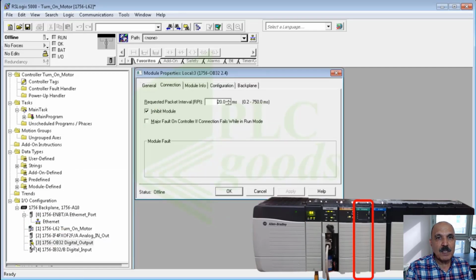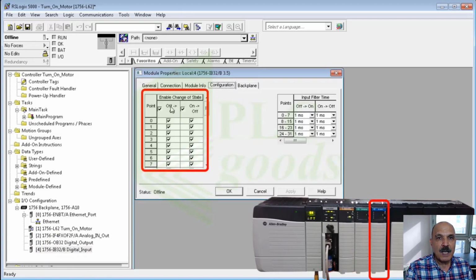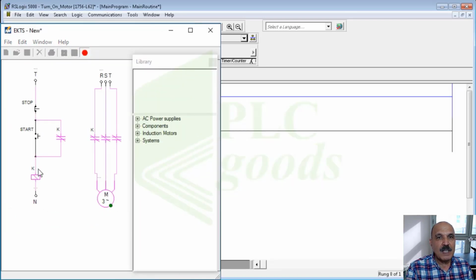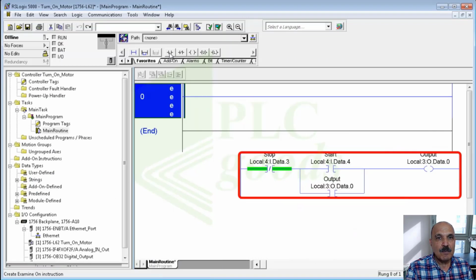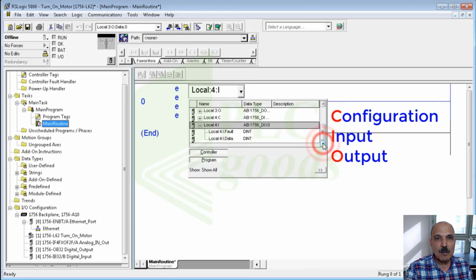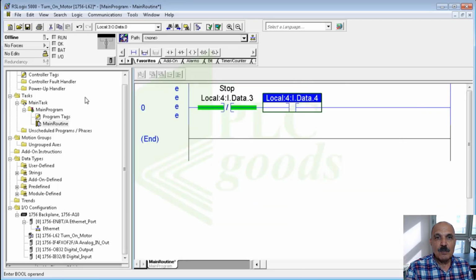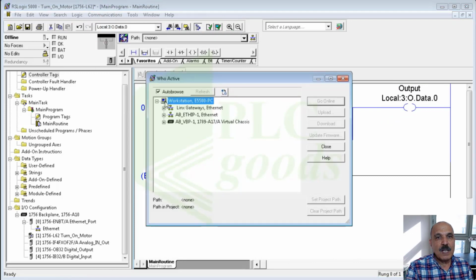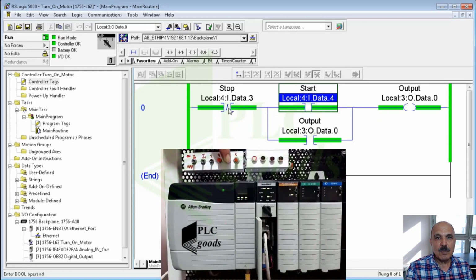I simulate a simple industrial circuit using EKTS software with normally closed and open push buttons and a relay controlling a three-phase motor. I relate that to PLC control, where we can get similar functionality without rewiring by changing the program. We write a basic program in RSLogix 5000 using module addresses and then compile and download it to the PLC. I show the logic, including how digital inputs trigger a relay to control a load.